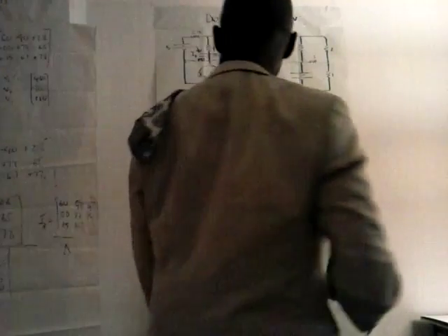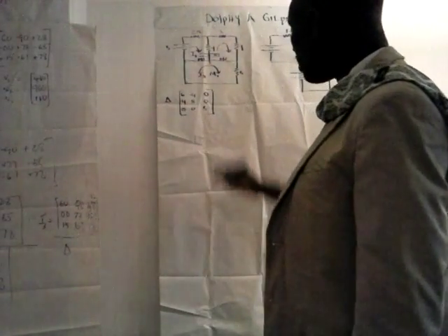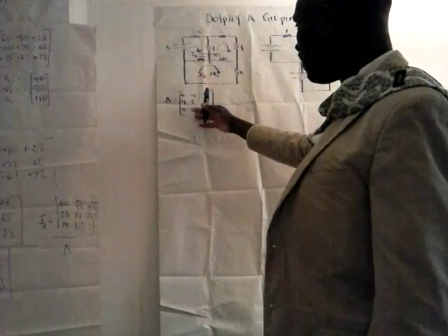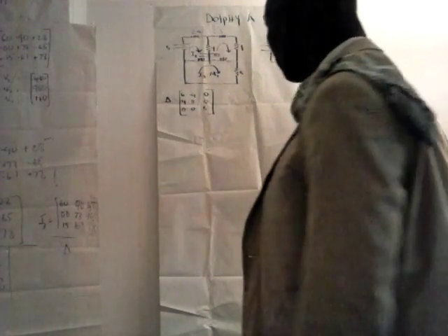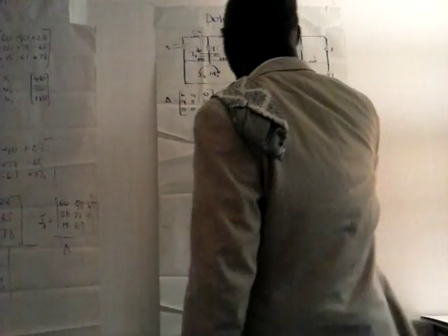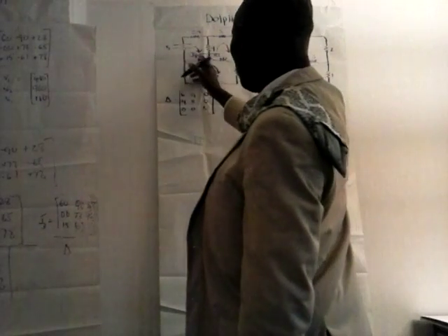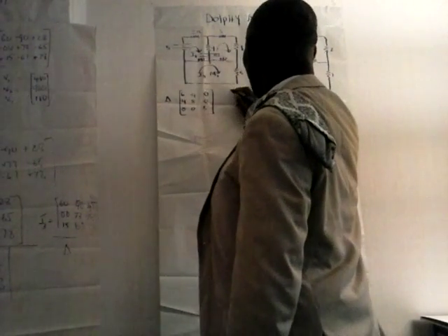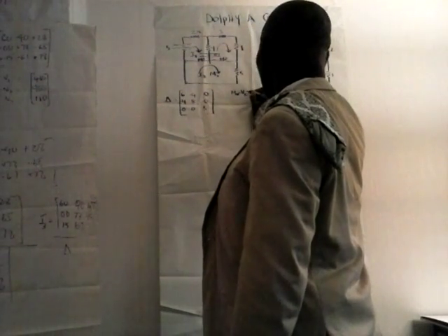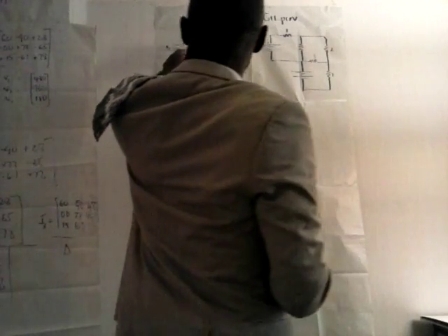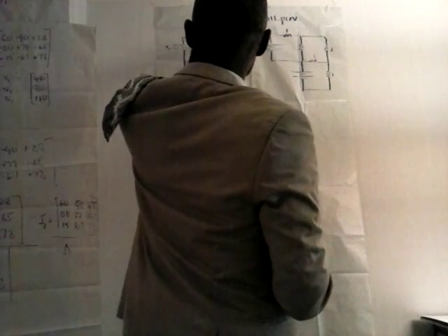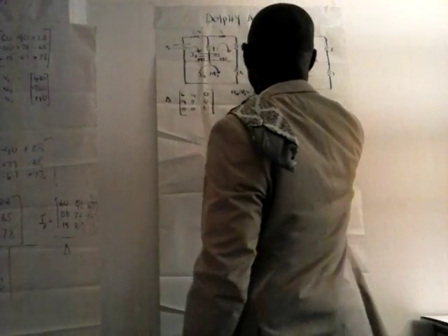So here we have put in the values of the resistances by inspection, and this calculation will be easy due to the small element values and the zeros that are in it as well. And so if you make the calculation for this, and suppose now we calculate the voltage in mesh 1, as V1 now, M1V equals V1, and that's equal to 5 volts, negative to positive, and this is positive to negative, so this will be minus. So 5 minus 10 will be minus 5 volts.